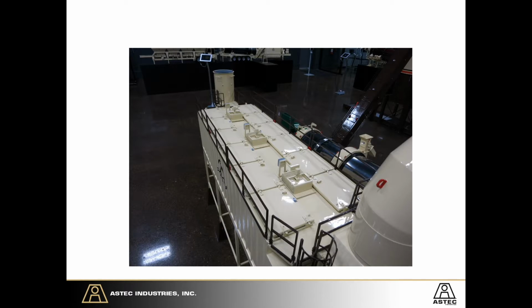Here's a top view of these turrets. As the capacity of that baghouse changes or increases, you would need to add more turrets, or you would take turrets away. Those turrets can be operated two different ways, either simultaneously or sequentially.